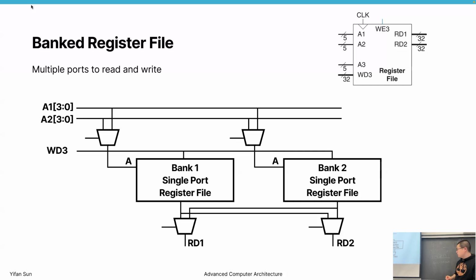Okay, so 128 banks, but you can either understand it as banks or as a separate register file for each thread, because they will rarely communicate. Communicating data from one thread to another is a relatively advanced instruction. Basically, coalesced memory access is related to this, so they are all interleaved in 32 banks. So the interleaving modulus is 32.